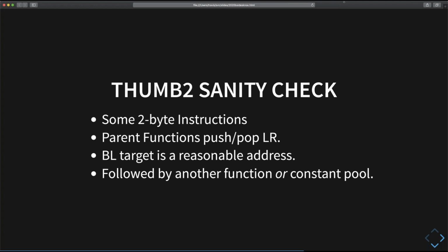In x86, you could have an instruction that contains a 32-bit word inside of it. In Thumb2, the longest instruction is only 32 bits, so there's no room for that constant to fit. So instead, you point relatively to the end of your function, where you have a list of all the 32-bit values you might want to load, and it can be fetched from there.